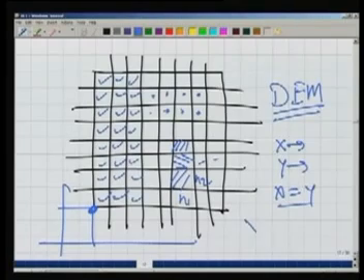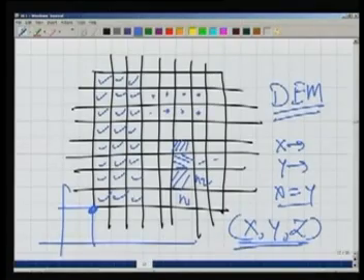So what we have achieved is that for each grid cell, we now know these three. The ground is now represented in matrix form or grid form, also called raster form, where the xy coordinates of the raster can be determined using the coordinates of one point as well as the sizes of the grid in x and y, and for each raster cell, the grid cell, we have the height there.